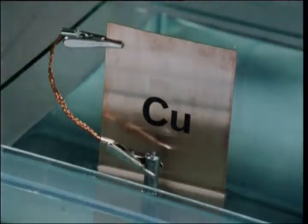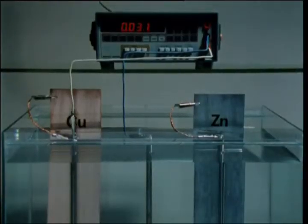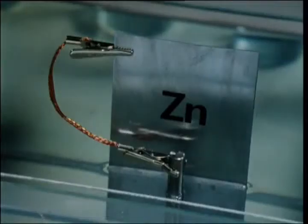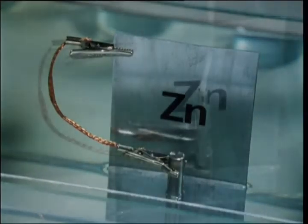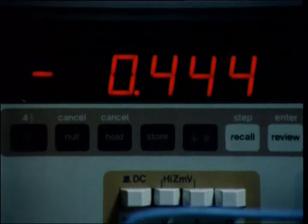When the steel-copper couple, which we've seen corrodes the steel rapidly, is compared with steel on its own, the potential of the couple is more positive. Conversely, when the steel-zinc couple is compared to the steel on its own, this potential is more negative, and the steel in the couple does not corrode.